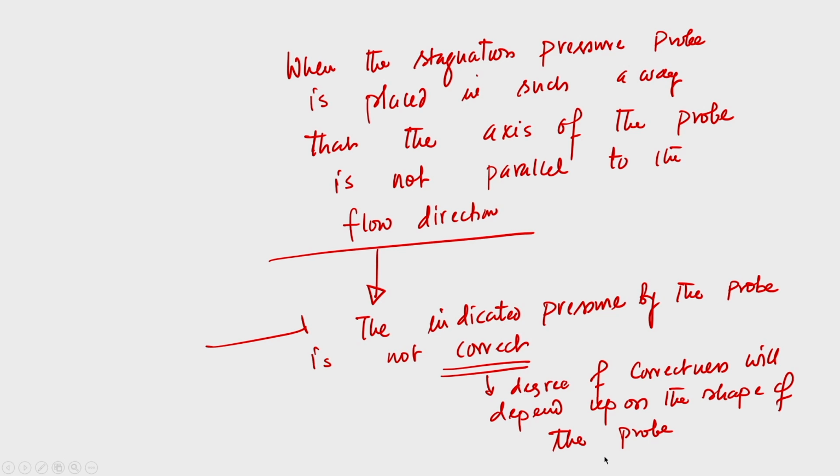See, the most important advantage of using probes is that we have seen we can measure pressure using gauges. We have discussed different gauges, from conventional ones to the low pressure gauges used for low pressure measurement, but these pressure probes are used for simultaneous measurement of static pressure and total pressure.